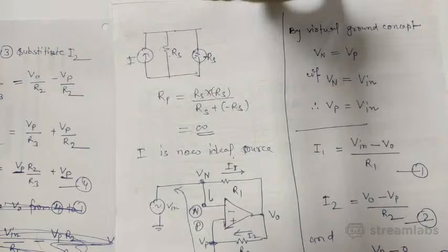Then design a negative resistance converter in series with the battery, and that will cancel out the positive resistance with the negative resistance, and the end result will be a combined circuit that will act much closer to an ideal voltage source without changing its output. And it will not depend on the load. So that is how we can make an ideal power source using the negative resistance. But we need a fine-tuned power source, and it should not change its load, its series resistance.